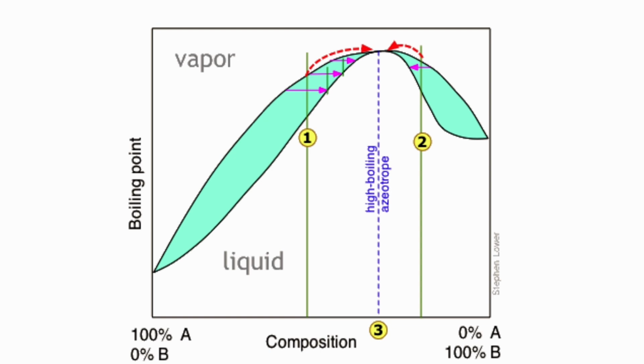Another cool example of this, with an interesting tie to our class, was a group of researchers who wanted to separate N-pentanol, cyclohexanone, and cyclohexene oxide, which are part of an oil, as a byproduct in the production of nylon. These chemical components all have similar boiling points, making it hard to distill and separate them. So for this reason, they tried using azeotropic distillation by adding water as an entrainer and then using Aspen Plus to model what would happen. Their results found that using this method of distillation could help save 7% of annual costs.